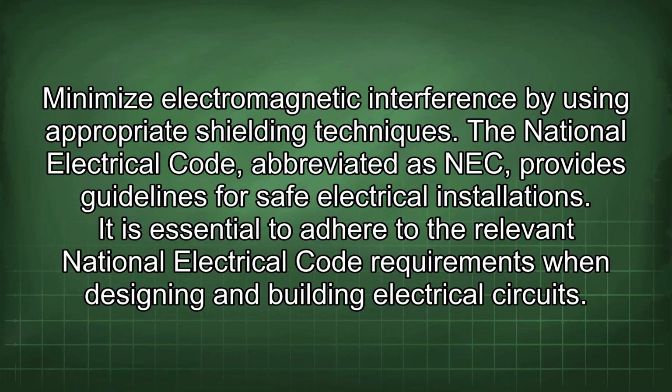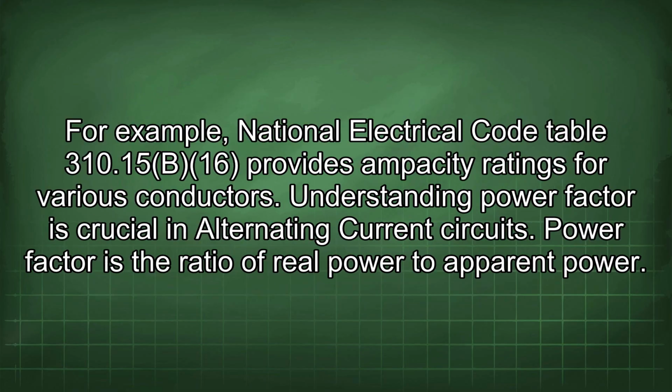The National Electrical Code, abbreviated as NEC, provides guidelines for safe electrical installations. It is essential to adhere to the relevant National Electrical Code requirements when designing and building electrical circuits. For example, National Electrical Code Table 310.15(B)(16) provides ampacity ratings for various conductors.